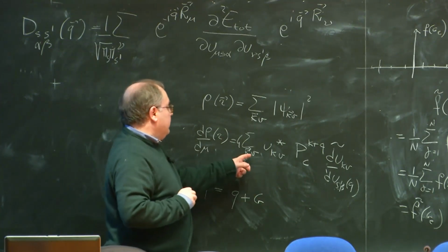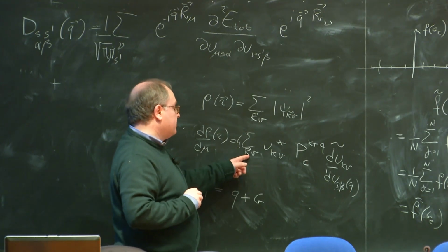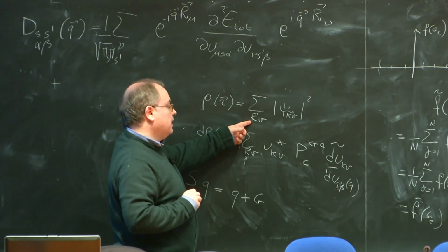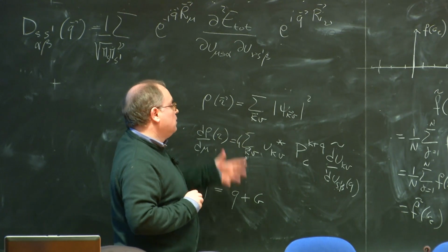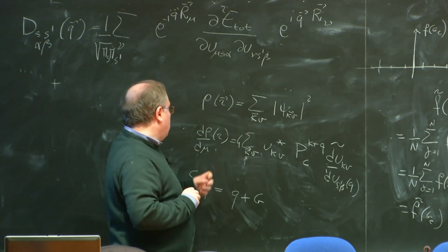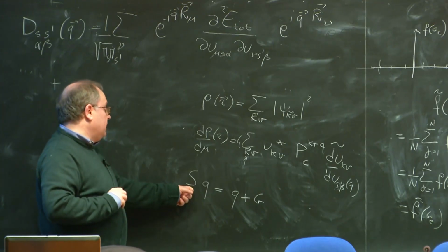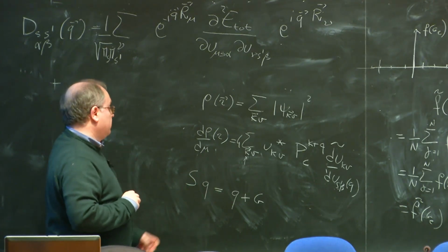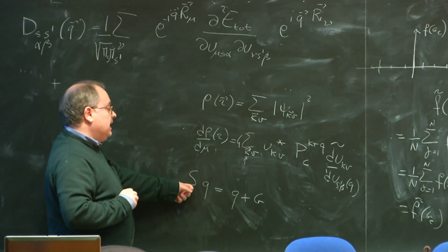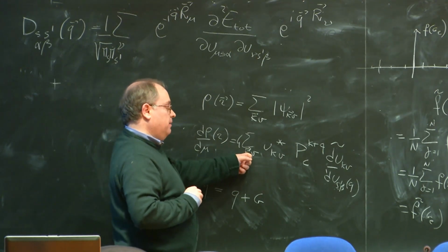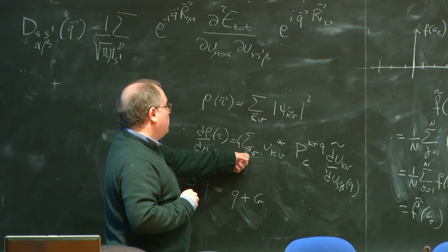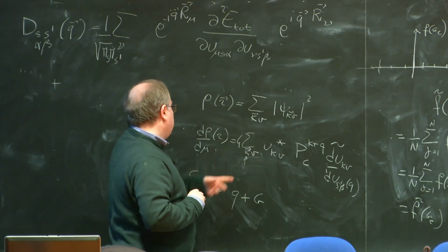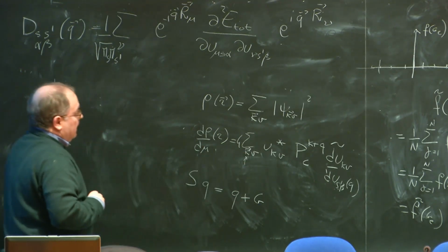And so the k points that you need here are more than those that you use for the self-consistent calculation, because they are reduced not with all the point group symmetry of your system, but only with the symmetry of what is called the small point group of the q vector. And this has less symmetry, meaning that this has more k points. And so the phonon code makes a non-self-consistent calculation on all the missing k points and on the k points k plus q. This is one choice.